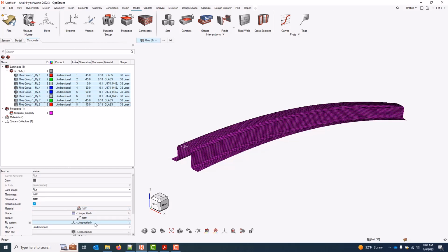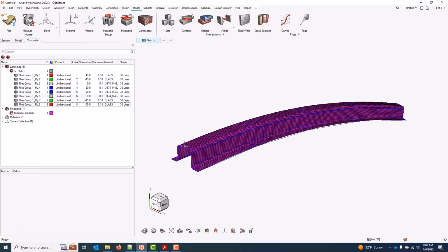The end result, if you left it, you'll still get a valid model. It'll end up just generating tables at the end as well. So generally, I prefer to do my material reference systems like we just did with an assignment onto the elements or property, depending on solver. Moving on, we'll convert this geometry-based shape data into element sets using the ply realization.